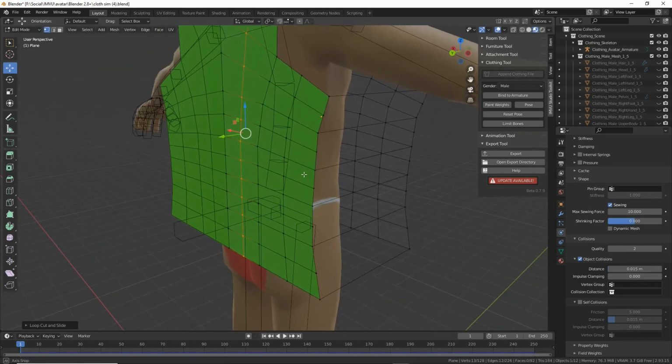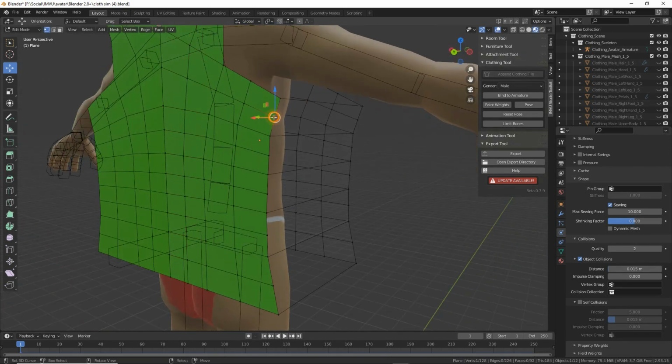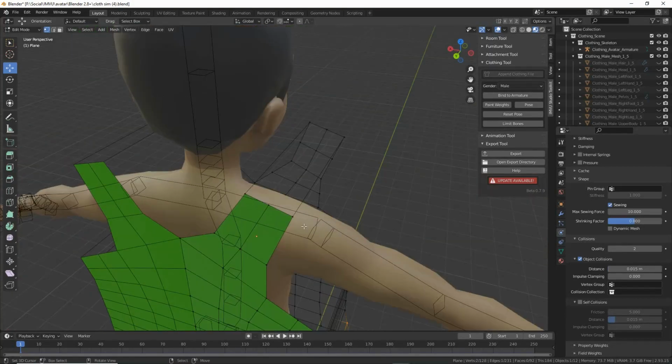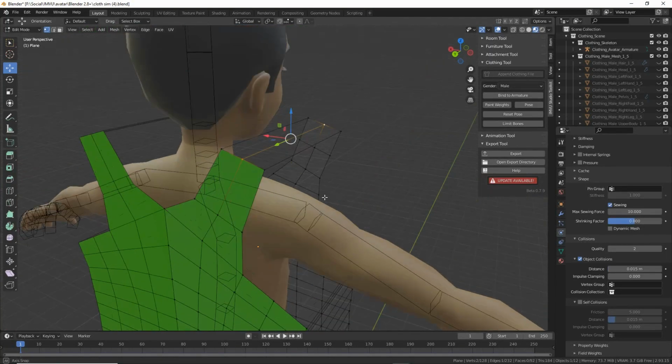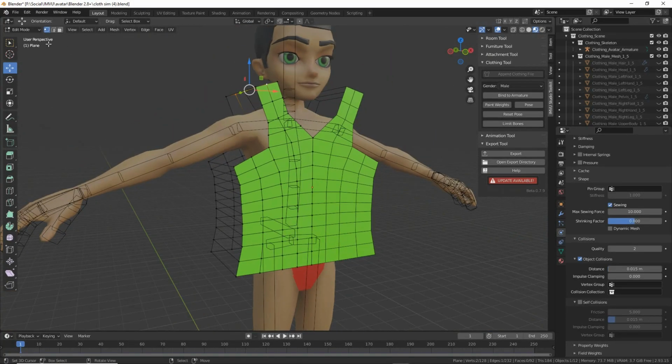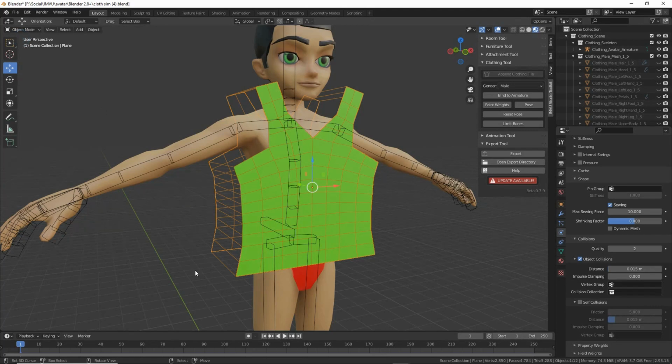And then what we need to do, join these new vertices with our new thread, so the F key, select our vertices, F. So we're essentially creating a thread between these new vertices. Then we can redo the simulation. So object mode.